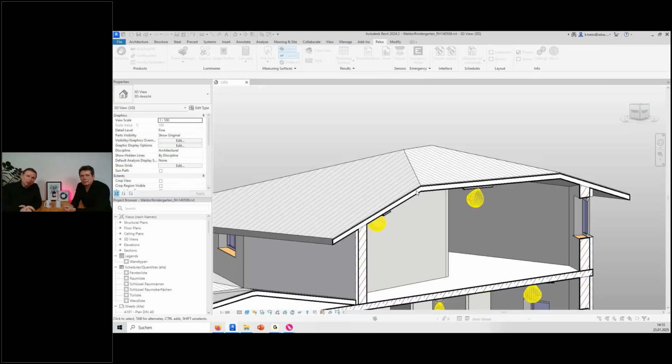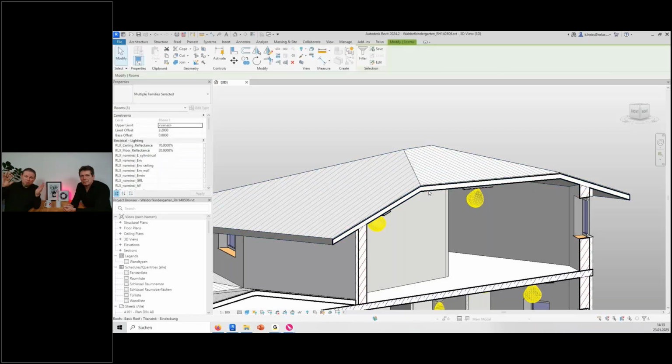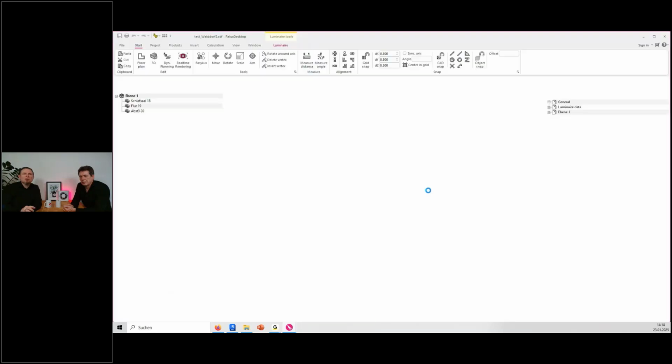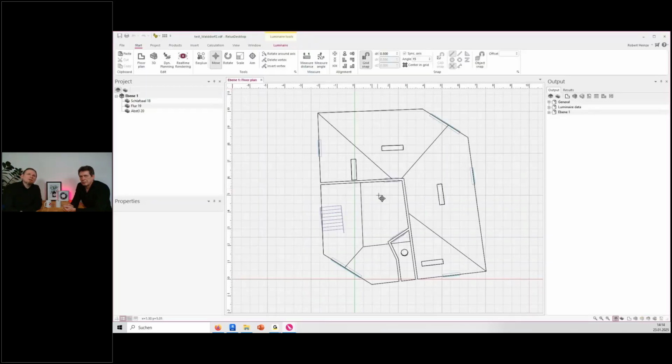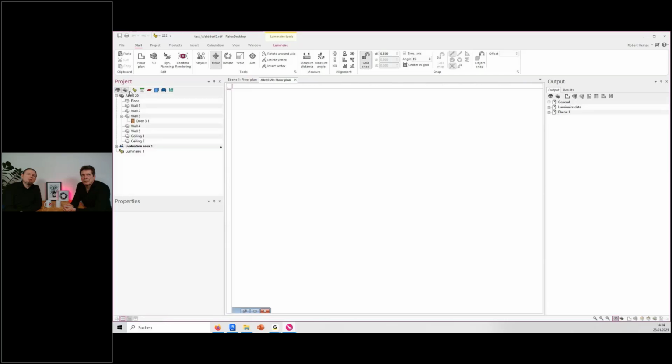You just have to be aware in Revit that you have the room container, or the room shape. That's also in IFC and also in Revit, a room definition volume object. And this also has to cover the complete seating to the top, so really to the end, and then you have a result like this, and it looks better in 3D.